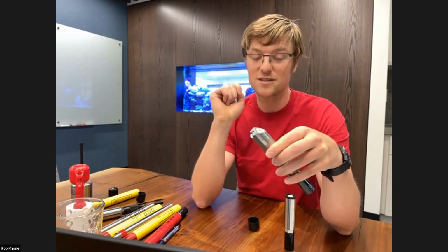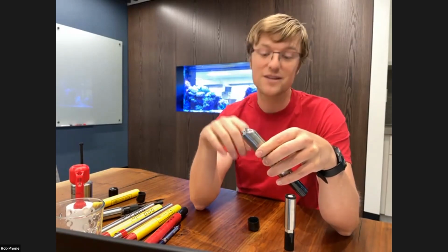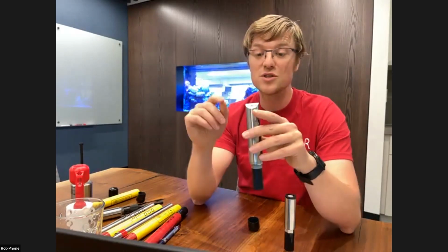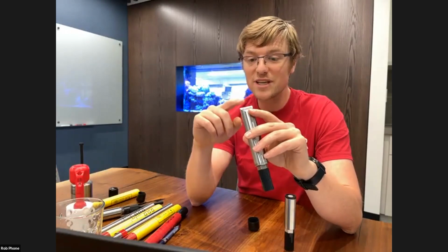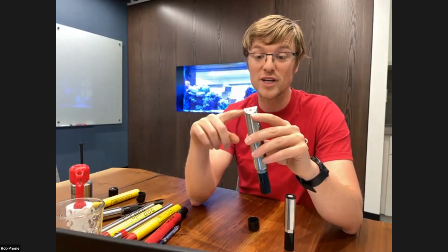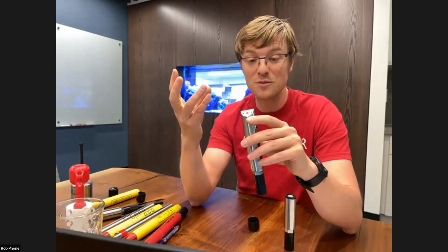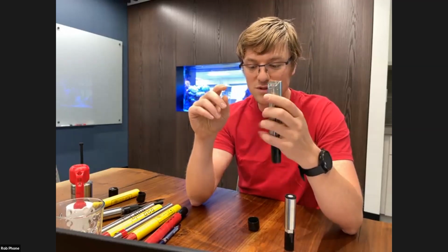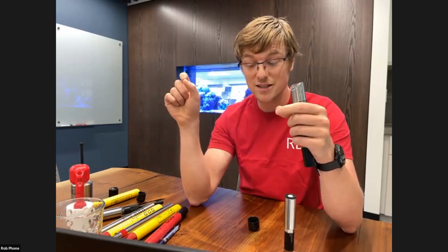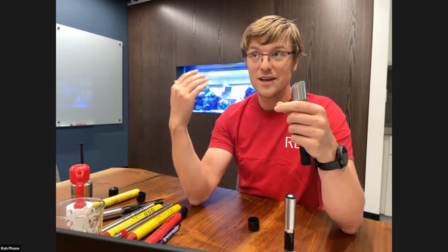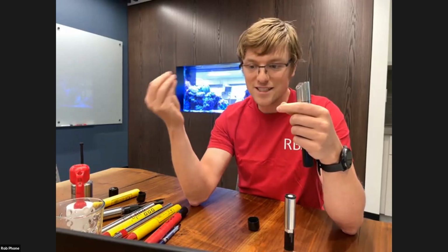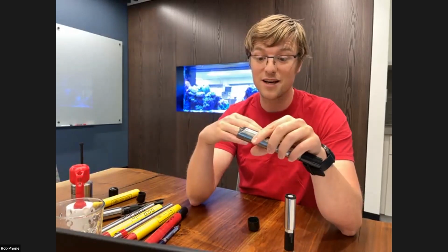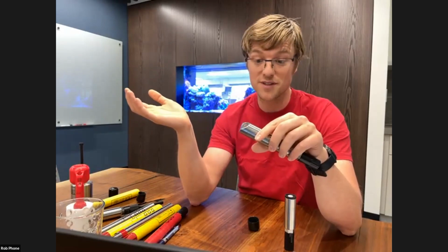And then we measure the light that's being fluoresced back to the detector. One thing some manufacturers do is you always want to compensate for other lights, so you can hit it with another wavelength of light that the membrane's insensitive to. The RBR's construction is such that we use two LEDs. One is just dedicated to the reference. If the LED intensity changes over time, we want to make sure that we measure that, so that mitigates some of the drift of the sensor.